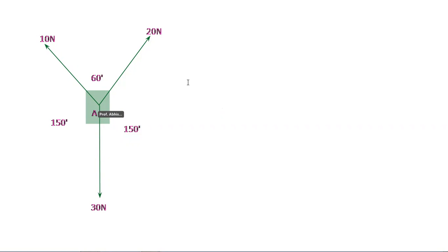Now what is Lamy's theorem? 10 Newton divided by sine of 150, equal to 20 Newton divided by sine of 150, and equal to 30 Newton divided by sine of 60. This is nothing but Lamy's theorem that we have seen yesterday, in yesterday's lecture. Lamy's theorem is very simple, and you should be able to solve the numericals based on it